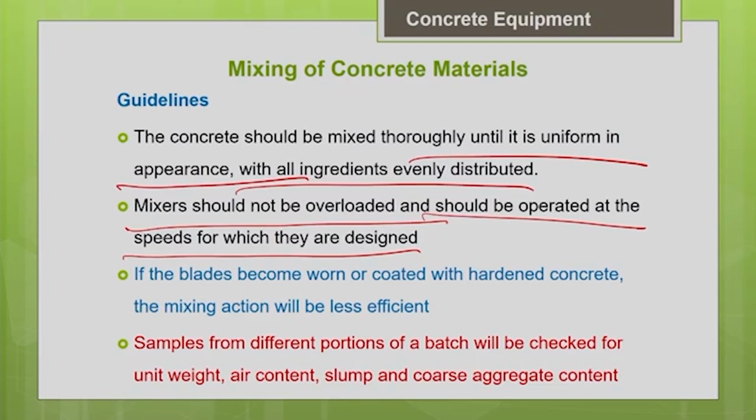You should clean the concrete mixers immediately, because if your blades get coated with hardened concrete, it is going to affect your mixing action. In many job sites you can see blades with hardened concrete, because the concrete mixers are not properly maintained, not properly cleaned after every mixing process. So the concrete might have hardened, and that will also affect the mixing efficiency.